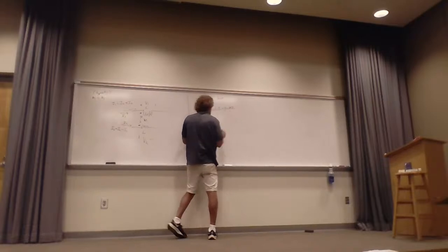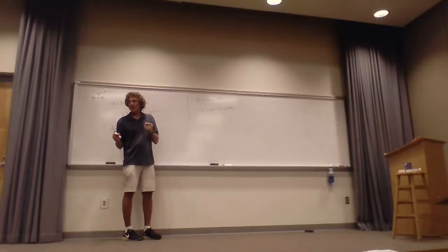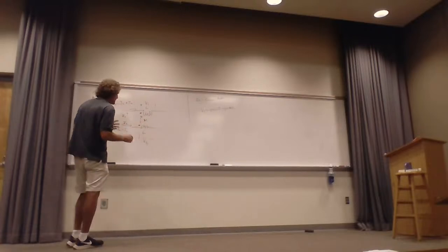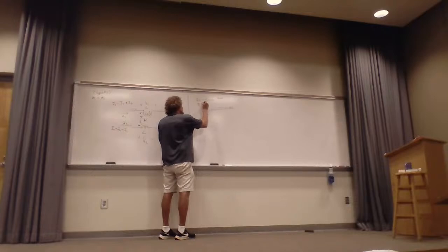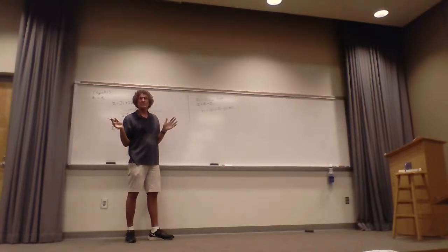Y'all with me? Now here, I'm just taking a look for common mode. And if I'm just looking at common mode, I1 is equal to I2 is equal to I common. You follow? I'm not even looking at the effects of this filter on the differential, just common. Do you see that? You go with that, Jacob?